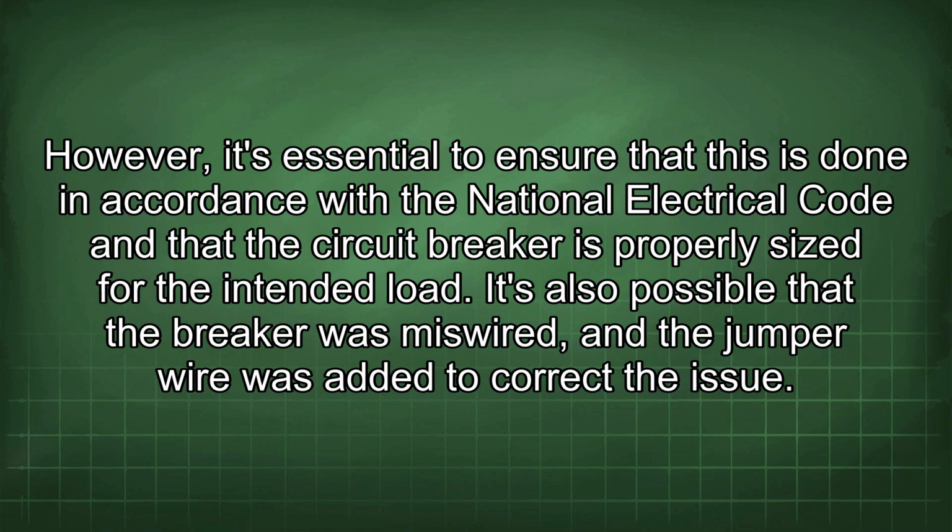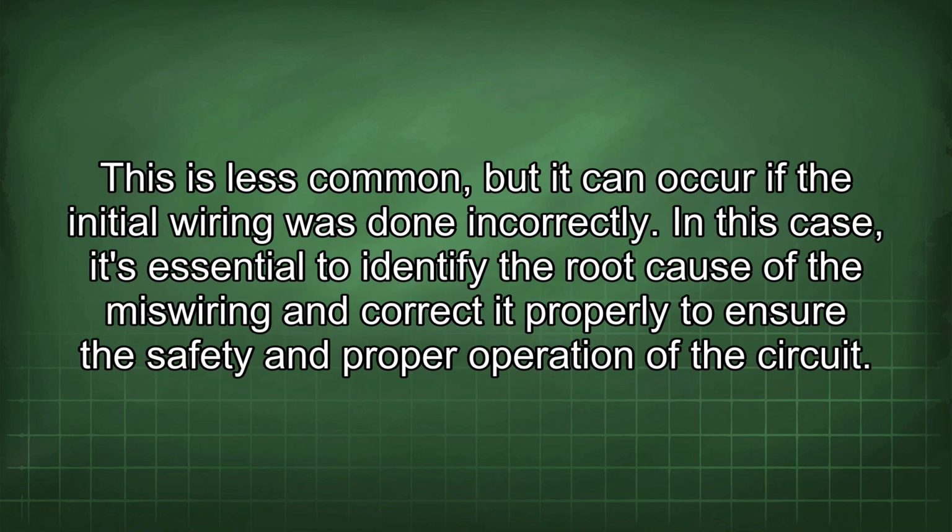It's also possible that the breaker was miswired and the jumper wire was added to correct the issue. This is less common, but it can occur if the initial wiring was done incorrectly. In this case, it's essential to identify the root cause of the miswiring and correct it properly to ensure the safety and proper operation of the circuit.